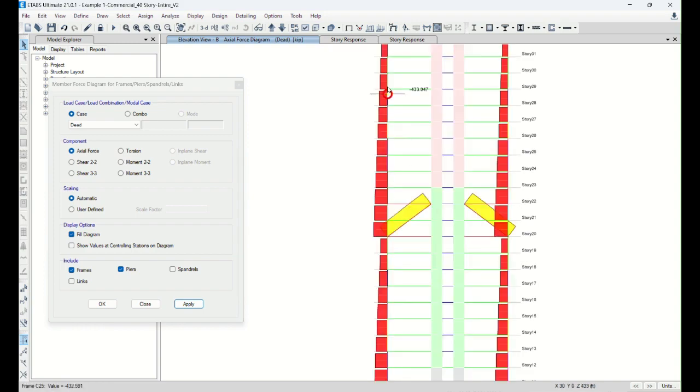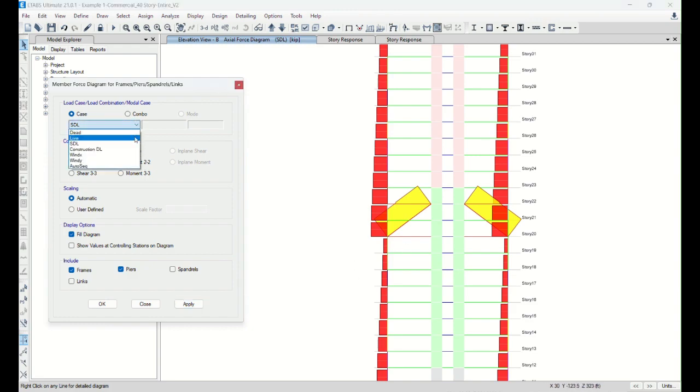See that the compression force is coming down. You lose some compression forces because this bracing is holding back and dumping those loads to the wall. But SDL as well, same thing. It's kind of straightforward, right? It's nothing special. But now I'm going to choose auto sequence analysis.